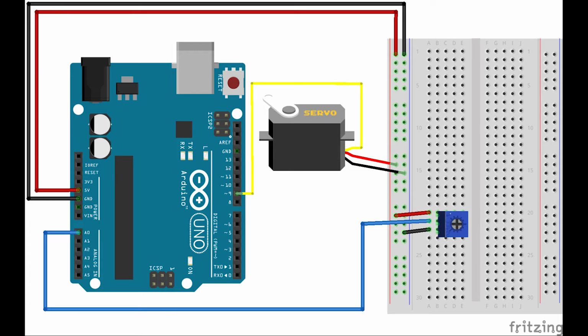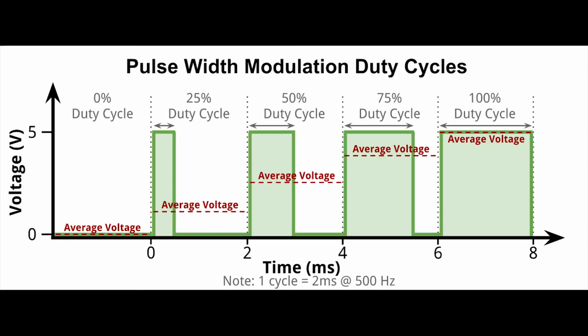The servo works in a similar fashion as the DC motor. Instead of the potentiometer controlling the speed of the motor, it will now control the position of the servo. There are not many components in this circuit due to most of the controls being held in the housing of the servo motor. The position of the servo is determined by the same pulse width modulation as in the DC motor. Now the length of the pulses determines the position. The servo motor library does this for you.